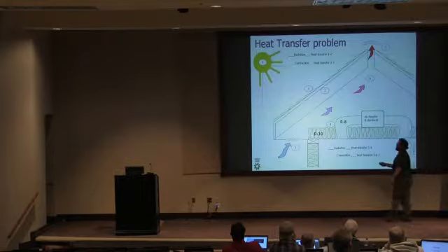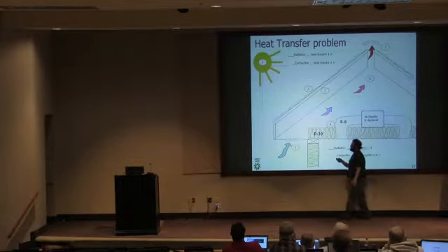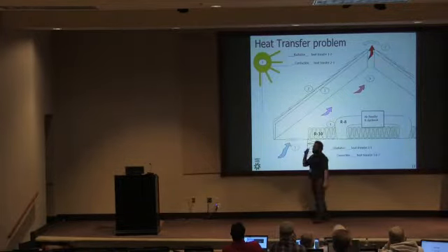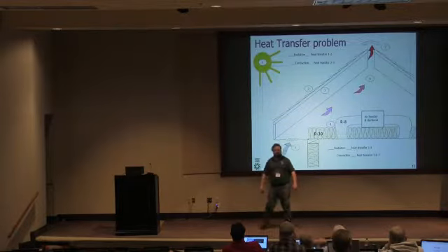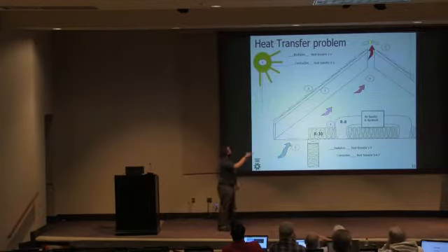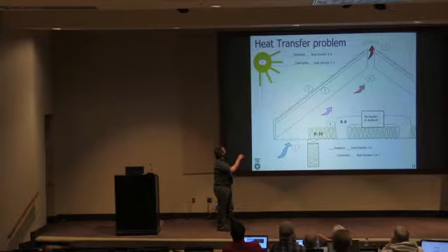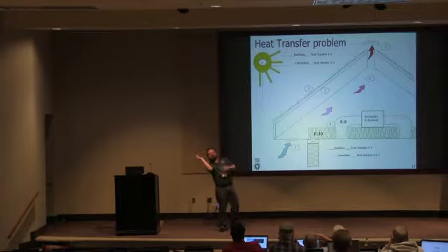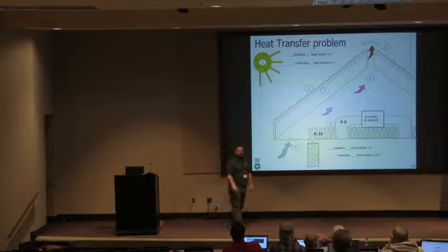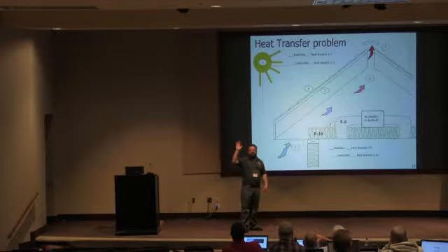Our attics and our roofs are really interesting places that experience all three types of heat transfer in homes. From the sun to the roof shingle, 1 to 2, is radiant heat transfer. That roof shingle is what? It's granular, it's black, it's leaned back to take lots of solar exposure throughout the day. It's basically a perfectly designed solar collector. So it gets really hot, absorbs, absorbs, absorbs. How many of y'all have gone up? I've done this several times.